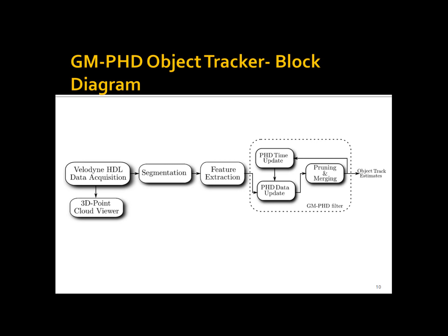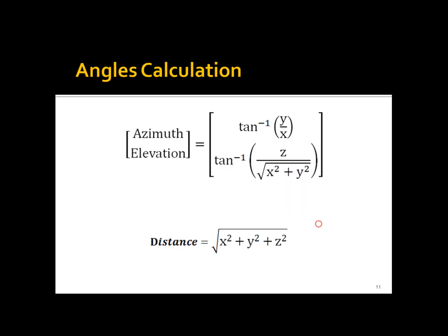As a result of the inefficiency and inaccuracy of all the models above, there is a need for a completely different approach: tracking. The objective of the multi-object tracker is estimating the state of an unknown number of objects based on the measurements of the object corrupted by noise in the presence of clutter. And so, here is the object tracker model. The sensor gives us three values: azimuth, distance, and intensity. Considering the calibration values, the polar coordinates are calculated and converted toward the right values of the angles and the distance.